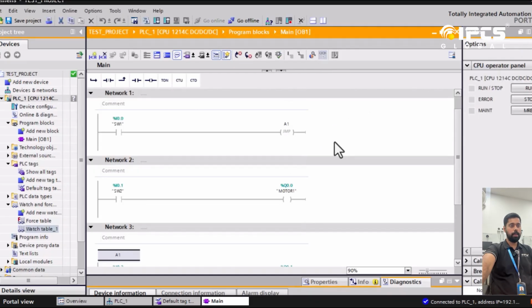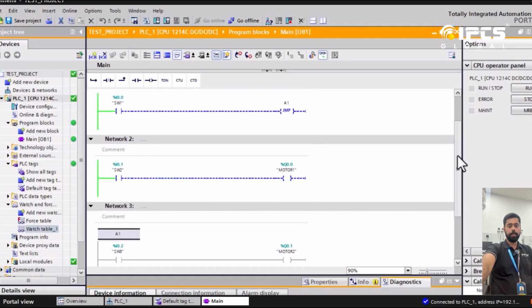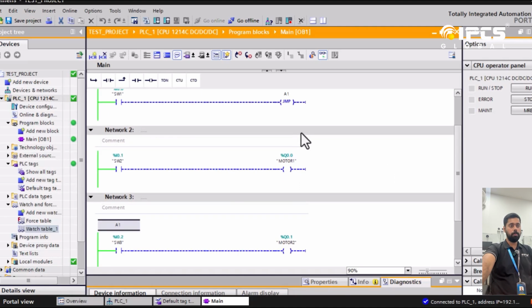Imagine that, as you can see on your ladder diagram, motor 1 is not working. Imagine you have a condition that motor 1 is not working, so the technician is being called out. During the time period when the technician resolves the problem connected with motor 1, we don't need that particular line to perform, right? So what I do is I'll just turn on the jump command.